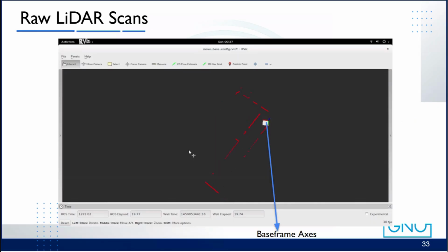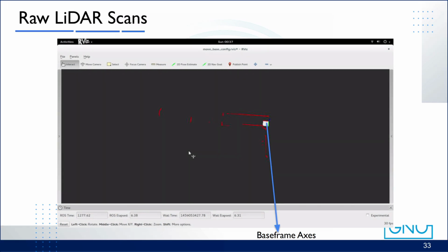This video shows how the LiDAR data appears from the car's point of view. The Hector scan matcher takes this stream of laser measurements, compares the scans between two consecutive timestamps, and aligns them with the map being built. At every step, it updates the robot's pose based on this alignment, ensuring that both the map and the pose evolve consistently over time.